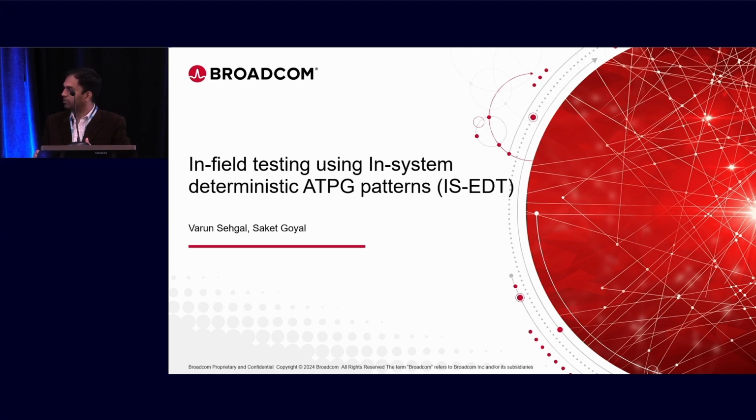differently. In-field testing or in-system test is when the SoC has been deployed at the customer end in the system, in the application. At that time, we don't have the luxury of access to all the IOs the way we have on ATE. So we have to run the patterns, whatever we want to run, in the system, with limited access to the IOs. That's where the in-system and in-field terms come from.